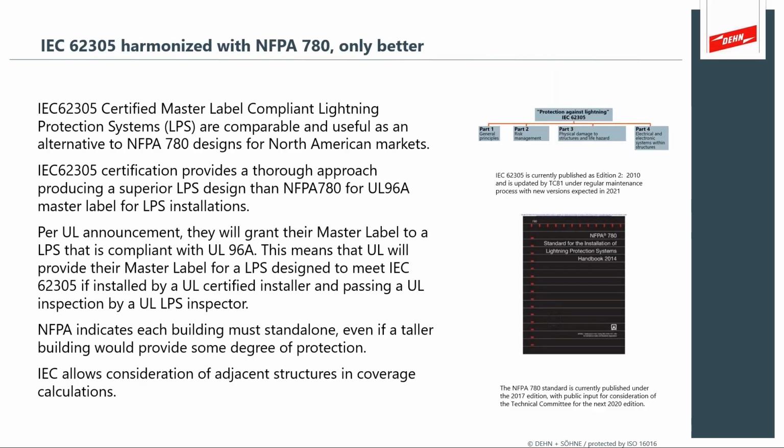So we want to introduce some of the more prevalent lightning protection standards, the IEC 62305 methods, and of course the NFPA 780 methods, which are prevalent here in the United States. One of the things I like to point out is that IEC methods are not that different from NFPA. I use the words only better because I think it's more thorough and it gives you a more rigorous approach. But there are a few key issues that you find.